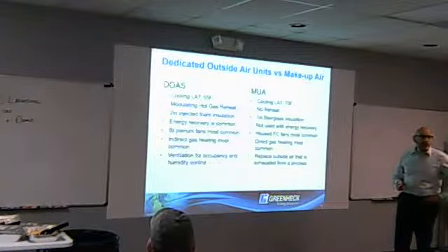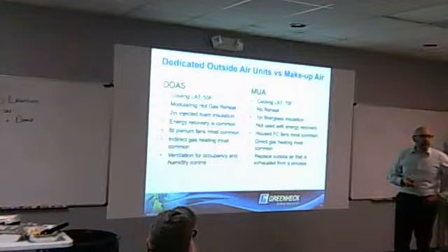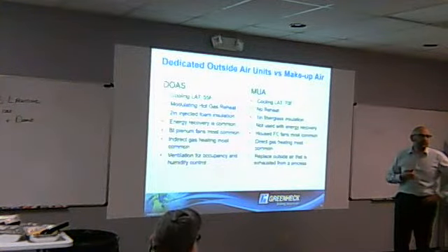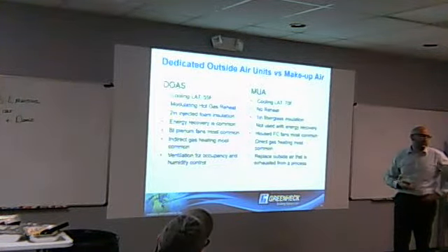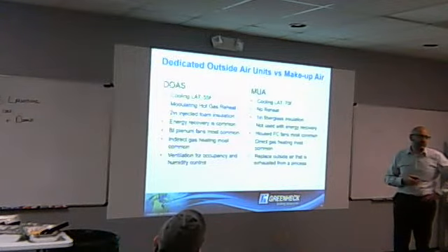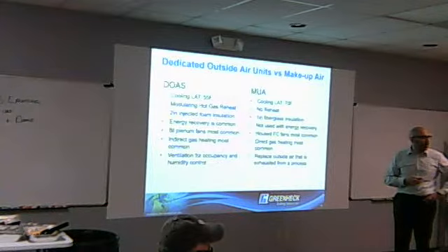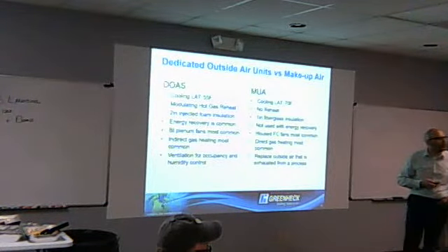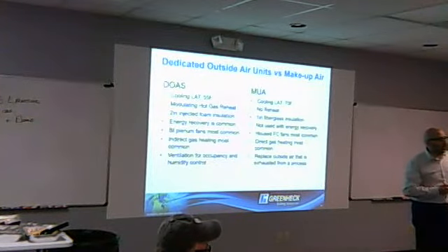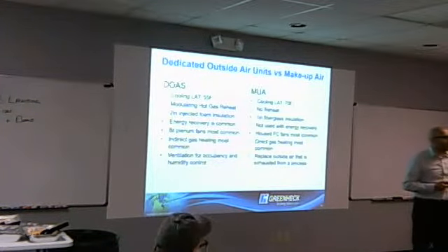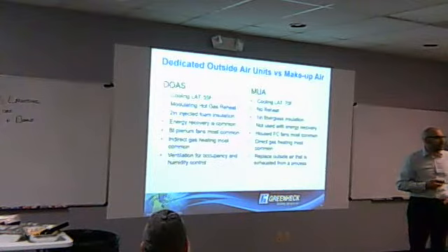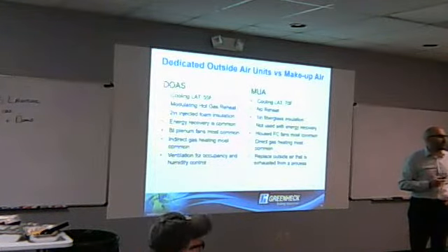Could it be heat pump also? There is an option to do like an air source heat pump. Or if you had another water source. Or water source, we have geothermal. We have geothermal in my school. We have all of our dedicated outside air on geothermal, and we use the geothermal coil as a pre-chill, like the 50-degree loop tap to get it cooled down before it gets to the coil. Which school system is that? South Range Local Schools in Greenfield. Oh, okay.